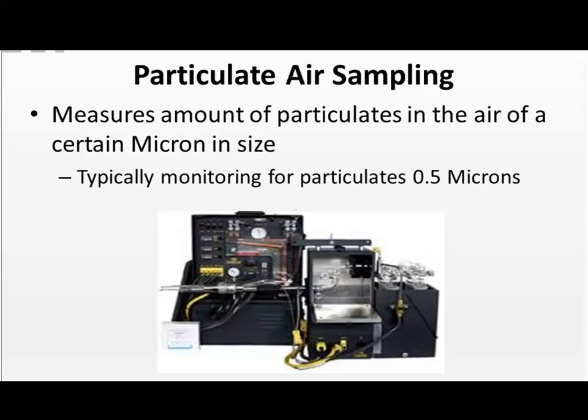Your particulate air sampling, we said a few moments ago, is done with laser particle counters, and we're looking at microns of 0.5 in size. This is what your particle counter is going to monitor. This is the level that your clean rooms are based upon.